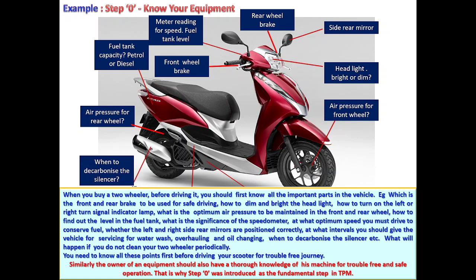the fuel tank, what is the optimum speed limit to be maintained to conserve fuel, whether left and right side rear mirrors are positioned correctly for safe driving, at what intervals you should give the vehicle for servicing for water wash, overhauling and oil changing, how to check the tightness of the brakes, when to decarbonize the silencer, etc. What will happen to the two-wheeler if you do not clean it periodically?